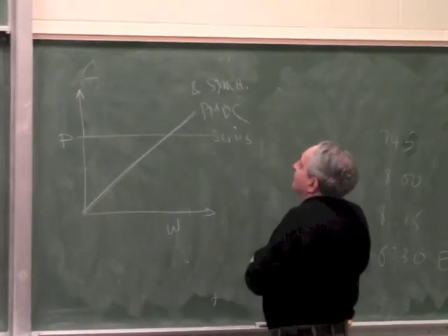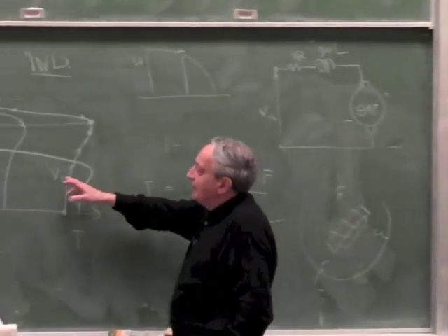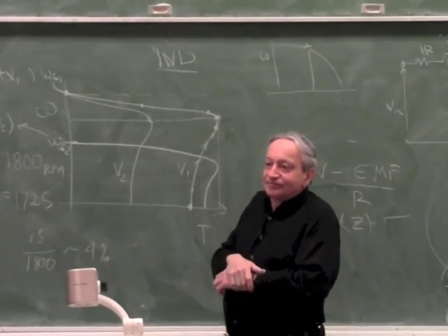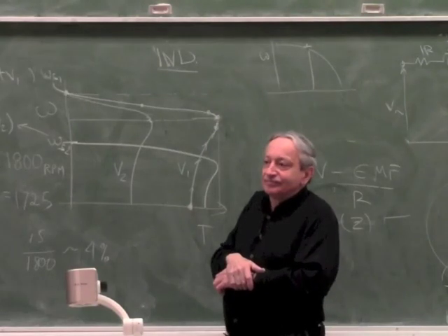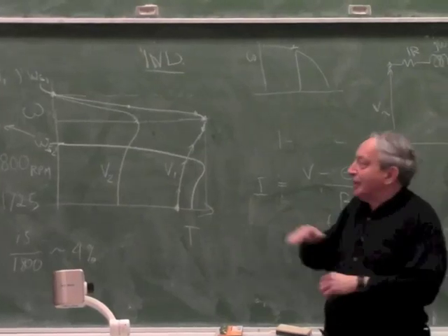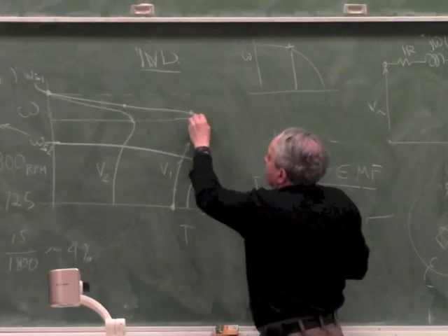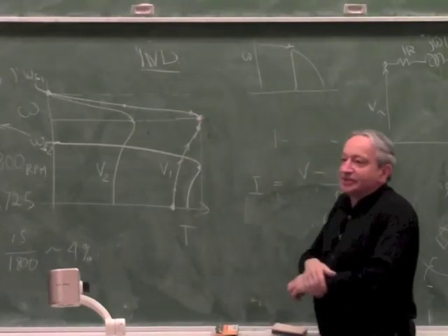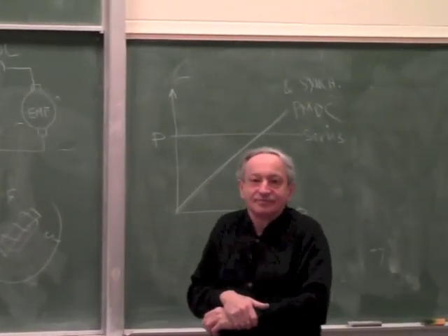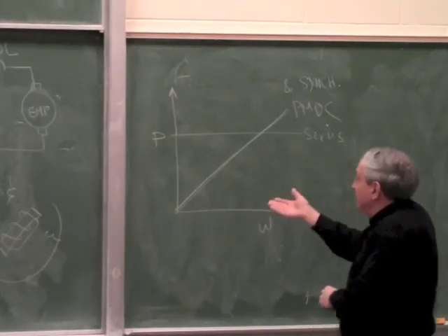synchronous motor. Okay? Now, what will this look like if I play around to keep the current constant? So I change omegas, but I always adjust the current, so this point is the same. The torque is the same, because I'm always running at full current. Okay? Close to linear? Oh yeah, pretty well the same.